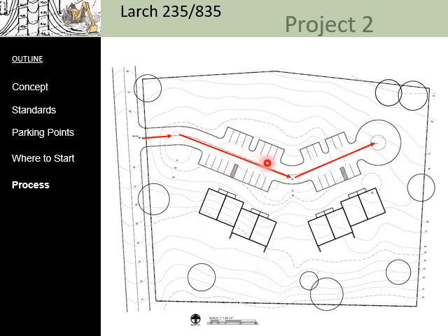You're going to start here, work your way to the building, drop behind the building, and you're going to discover something doesn't work well. And you're going to want to make some changes. So the question is, where can you make those changes? And as we've discussed in previous exercises, you can make a change by changing the elevation here if you wished. You could change the slopes between the parking lot and the building. You, in this case, have the option to add stairs.